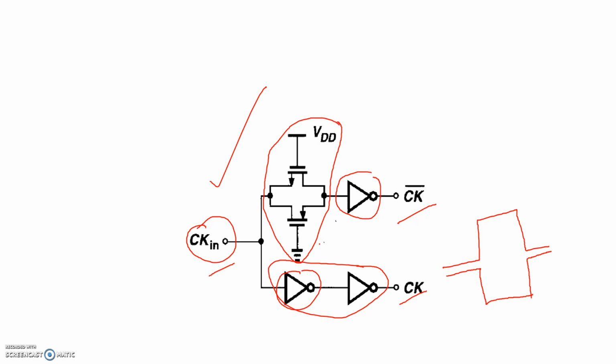Suppose they ask you how you can generate complementary clock, and if you directly say that by simply using one NOT gate, then that answer will be wrong, because even a very small amount of delay will affect a digital circuit a lot. Okay, so you should have a clear idea of these topics: TG logic, propagation delay, and these concepts.